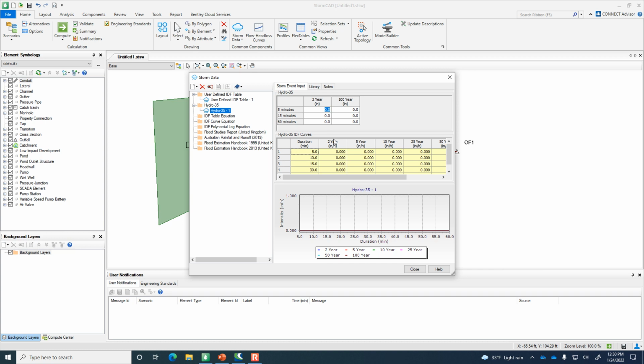On the handout I gave you, this is the third slide, where it has the depth for the 2-year. The 5-minute is 0.419. Now the 15-minute duration, 2-year, 0.799. Boy, that is a little bit blurry. The 60-minute duration is 1.31. Okay, now we'll put in the 100-year storm. The depth for the 5-minute is 0.755. For the 15-minute is 1.41. And for the 60-minute is 2.73.